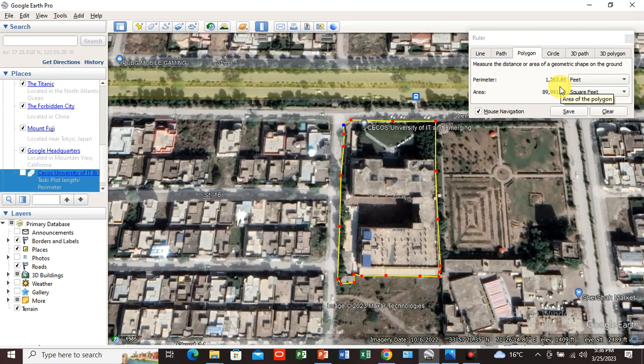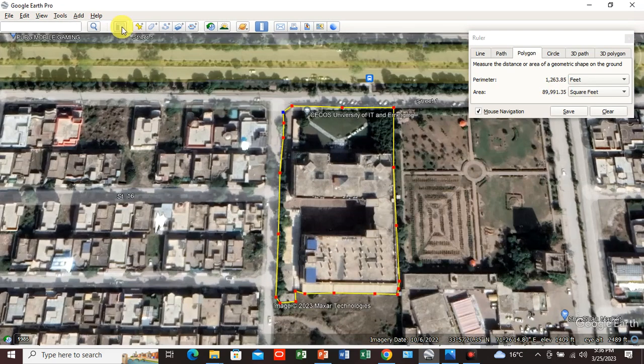Look, the polygon option, which is in the ribbon, this is a sidebar. I've highlighted it, and in the ribbon, this is the ribbon, and tab number 3 is the polygon option. We have to cross check the parameter and plot length with respect to the show ruler option, which is more accurate, and the polygon option. We will check the plot lengths, right? With show ruler, we will check the plot lengths. So which one is more accurate, which gives more accuracy? So let me show you.